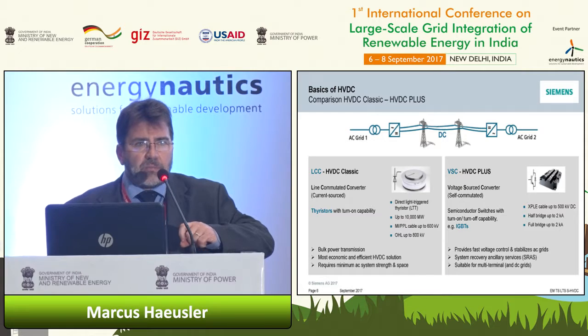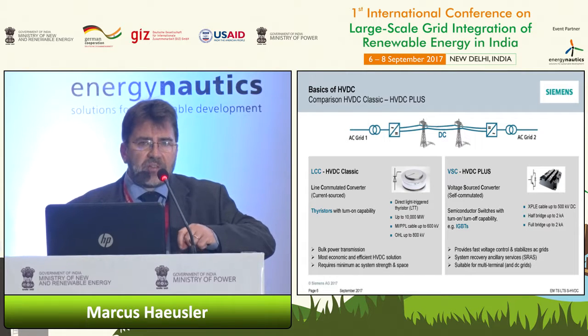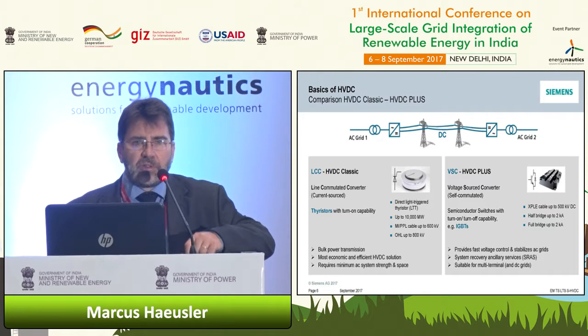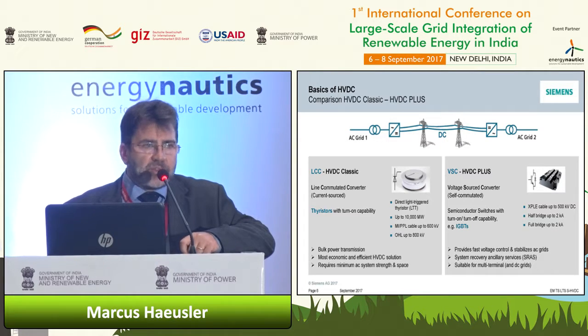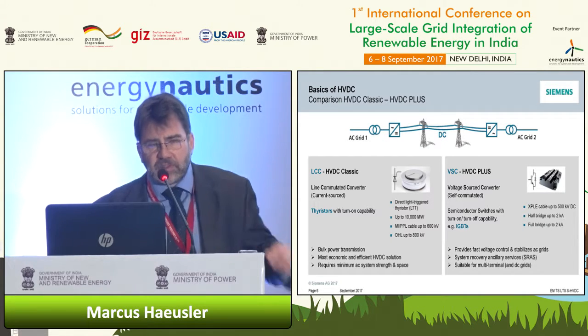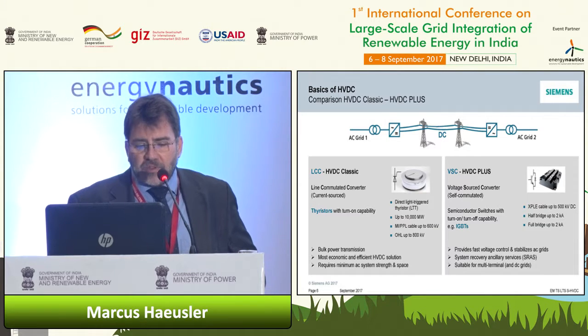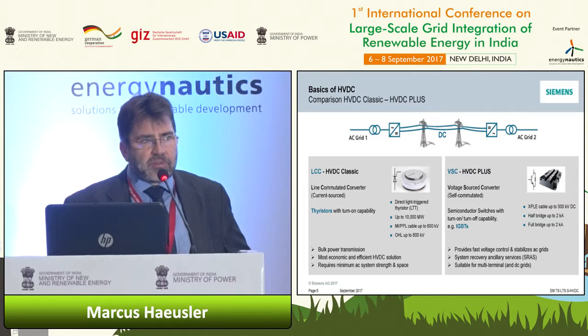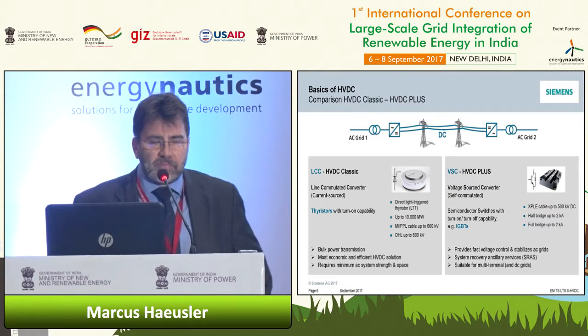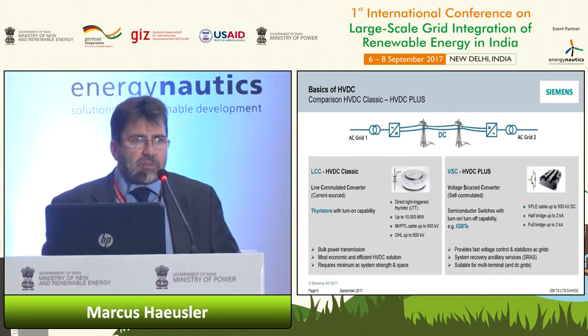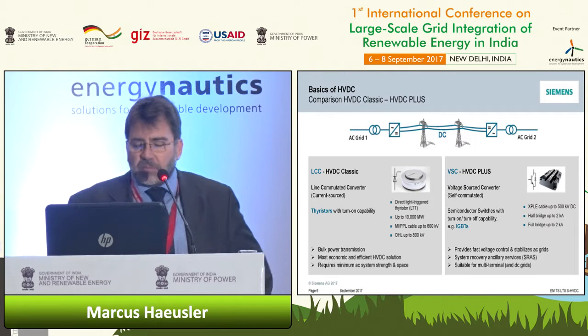However, there's one restriction, and that means that this technology is not suitable for all applications, especially if we look at some applications for renewables, where the system strength has to be at a certain level. Also, some requirements are there regarding space, and I will give you some examples to give you some impression of this. The disadvantage of these powerful thyristors is that they can only be turned on. They are turned off by the system strength, or by the AC system.